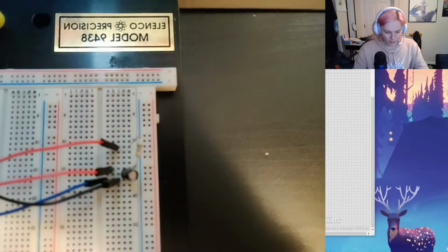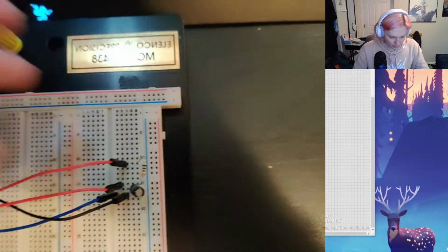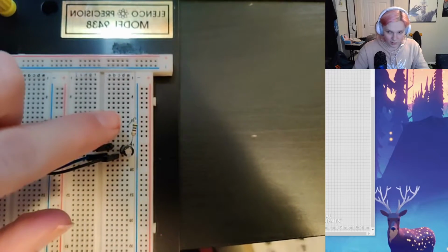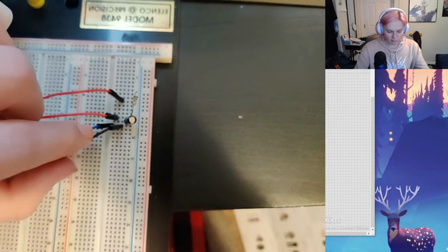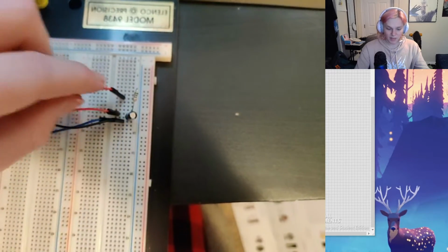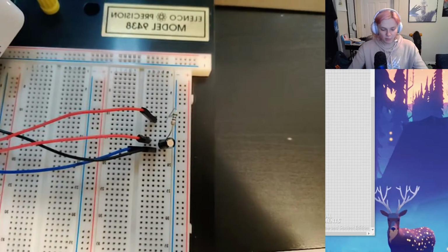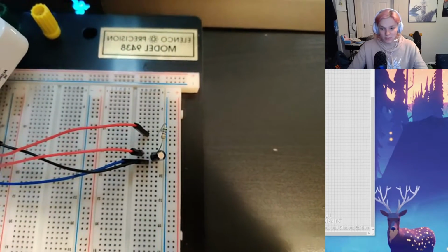Okay, so now you can see our output is this top line here, which is going to output the audio clip as a voltage into this resistor. Then we're going to read the voltage across this capacitor so that it will act as a low-pass filter. And we will play back our low-pass filtered audio.